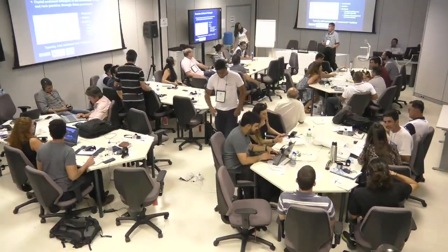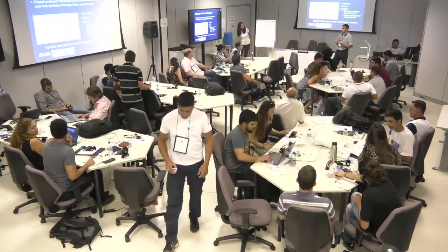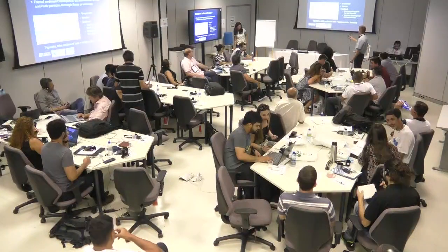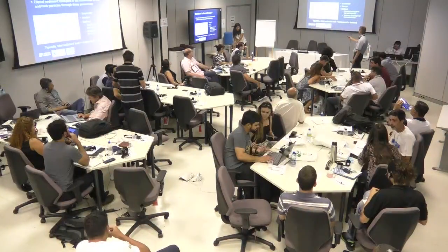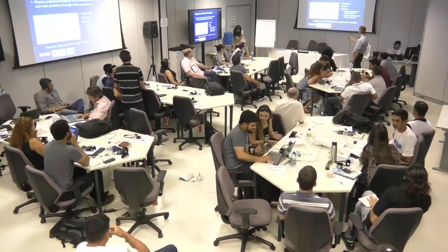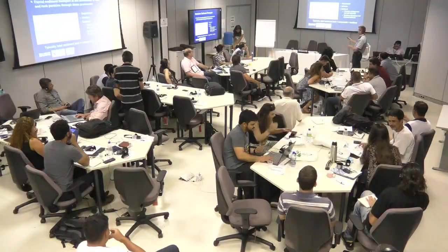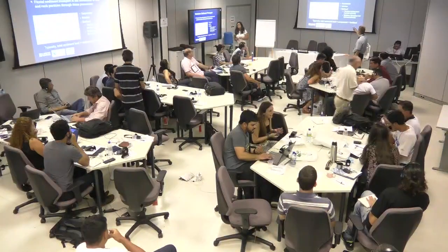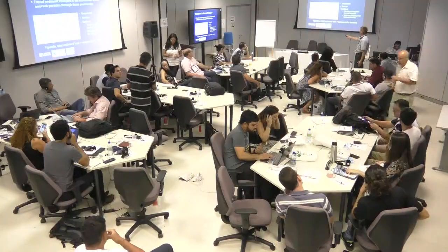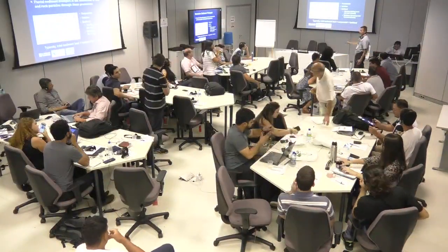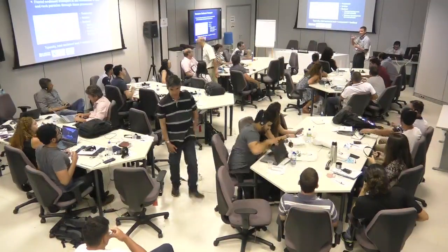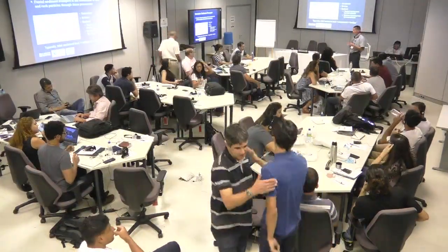All right, so bed load sampling is essentially getting at the material that's either saltating or rolling across the bed. It's material in movement. So similar to what we've been talking about, collecting suspended samples, we have samplers that will collect the bed load, the material moving along the bottom, because as you know, the suspended samplers don't reach all the way to the bed.